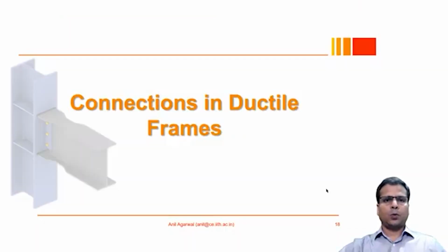So in this lecture, we will talk about connections in ductile frames. We require ductile frames, especially in seismic conditions. When we design a structure for seismic loading conditions, the seismic loads are typically so high and they exert such a large force demand on the structures that it is unreasonable to design them for elastic behavior. Because if we want a structure to behave elastically under the most severe earthquake that it can expect in its life, then most likely the structure will become so heavy, so bulky, that it will be unusable.